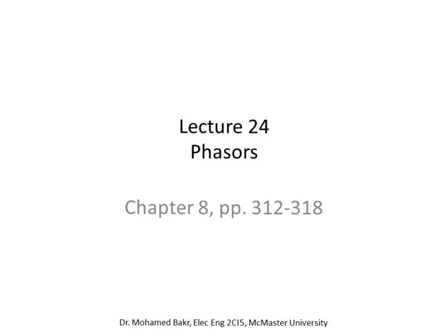In this lecture, I will go over phasors, and phasors are related to the complex forcing functions and the complex response functions we talked about earlier. We obtain them by omitting the e to the j omega t part, and I will show you how we can use them to analyze different circuits.